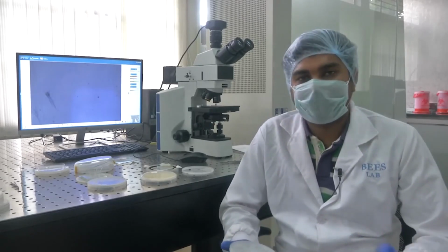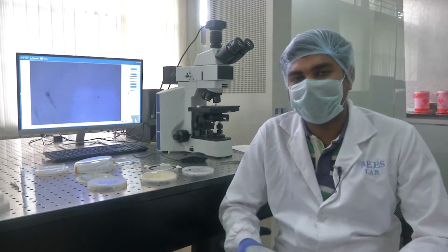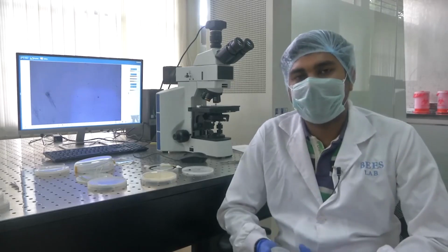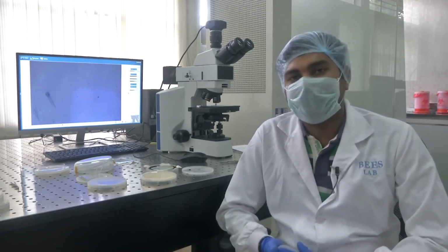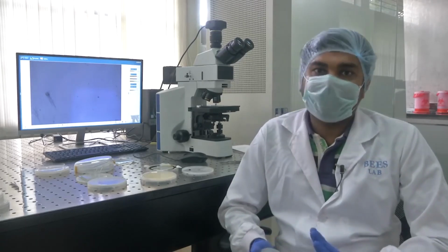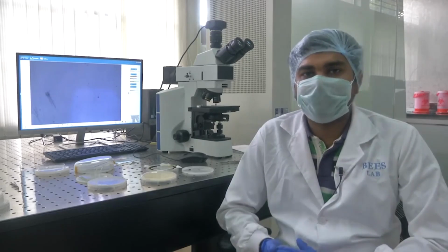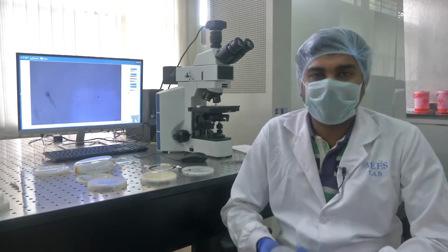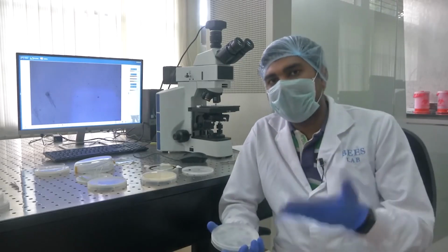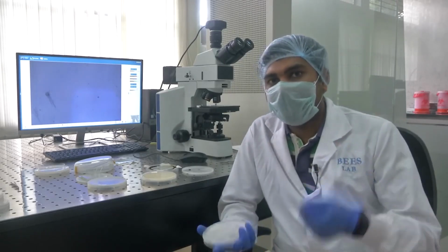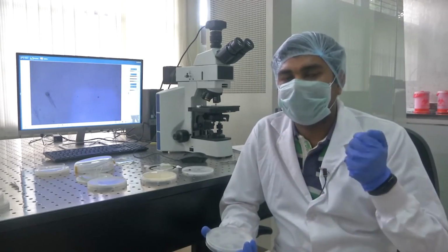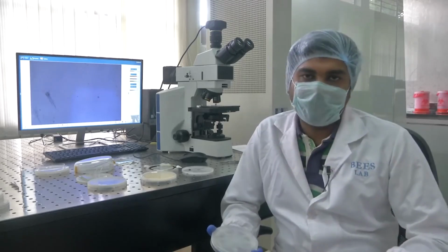I think the lift-off process has been covered in the lecture course before, so I will not go into details of it. The basic idea is that before you deposit the material, that is platinum itself, you do lithography. After coating photoresist onto your substrate, you do lithography, pattern transfer onto your substrate, and then on the patterned substrate you deposit your material, in this case platinum, and then you do the lift-off process. The photoresist will come out, and while it comes out, it will take away the platinum from places where it is not required. That is the overall idea